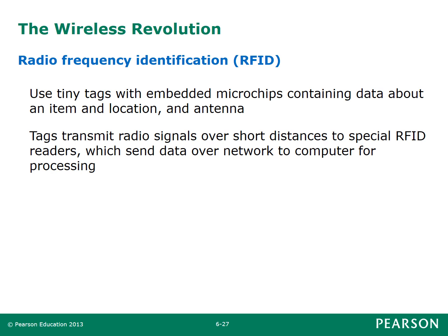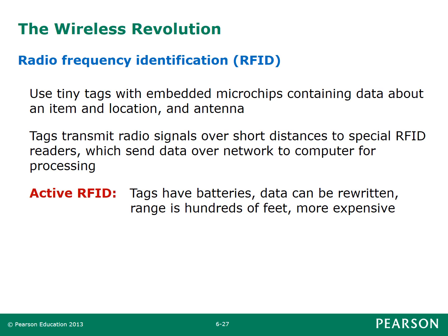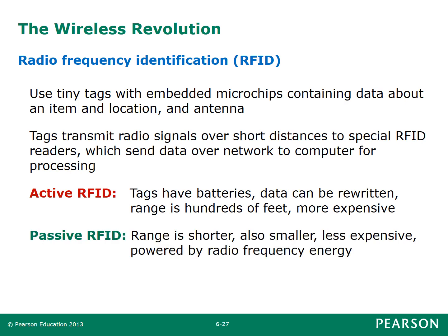RFID transponders can be very small. The coupling is done by magnetic fields generated by the reader within a short range, or by using high-frequency radio waves. This is used not only to transmit data, but also to supply the tags or transponders with energy.